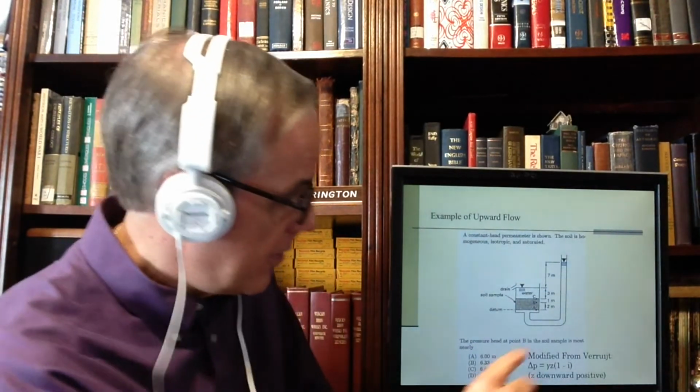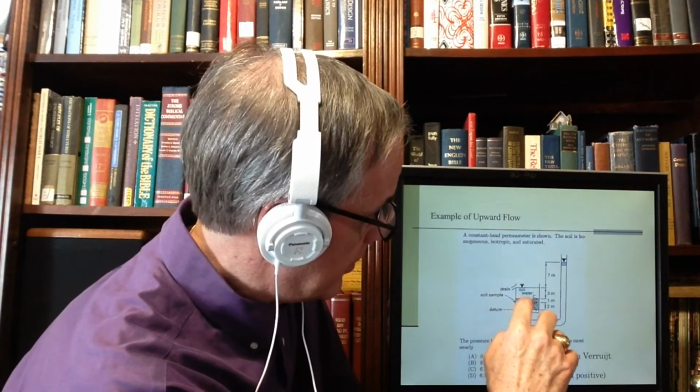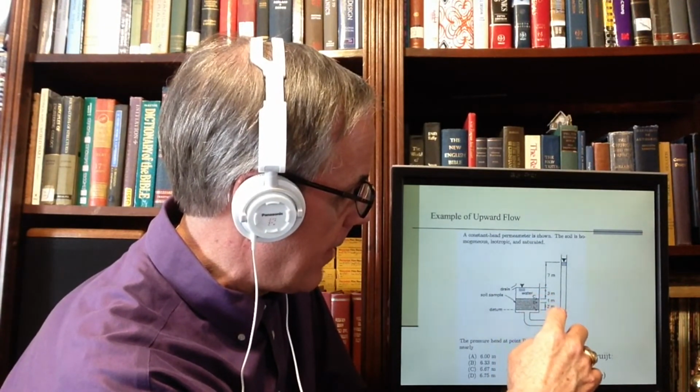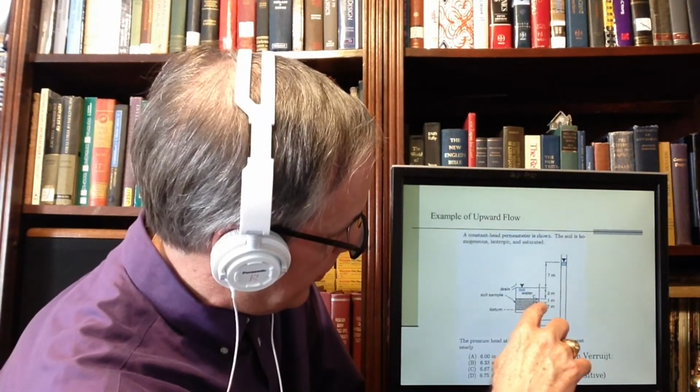If you noticed all the effective stress diagrams up to this point, the variation within a layer, the variation in effective stress, the variation in pore water pressure, is uniform, is linear. So the simple way to solve this problem would be to consider that this is 13 and this is 3, and that's linear. You could figure out the point at B, and I would invite you to try that.